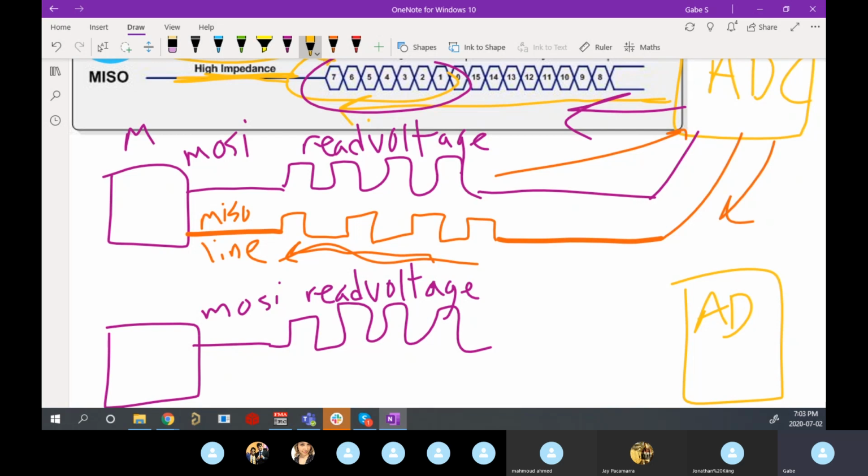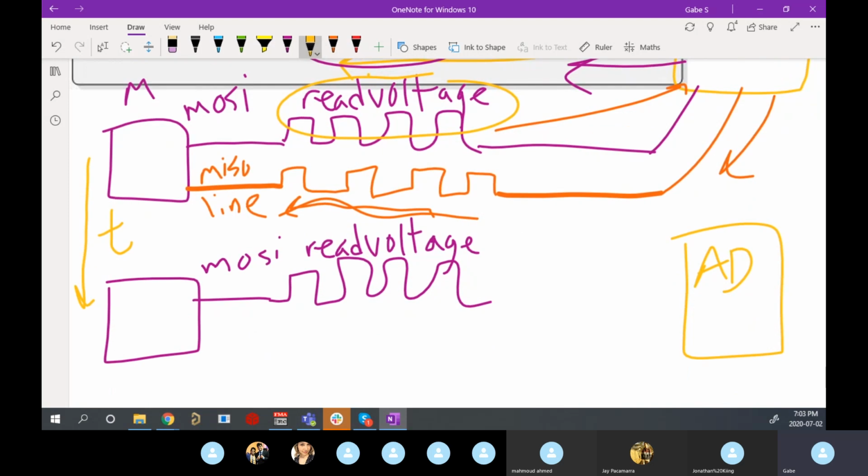We said, so this is earlier in time, so time is progressing this way. The ADC knows it wants to read voltages, it's just waiting for more data to come so it can send. So as it gets its second message, now it's actually sending those voltages.